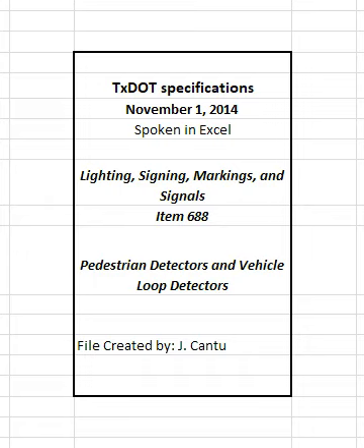3.2.3 Loop wire color. Use the following color code unless otherwise shown on the plans. Use white for the first loop on the right followed by black, orange, green, brown, and blue. Use the same color for all loops in the same lane.